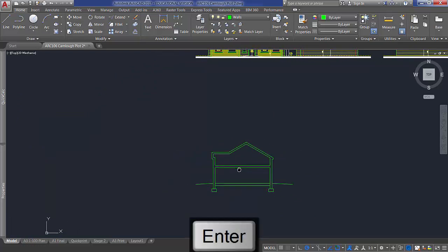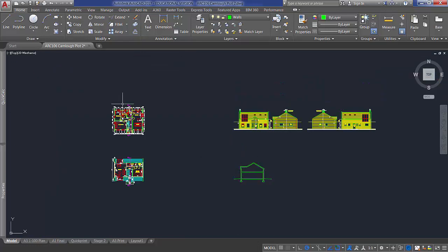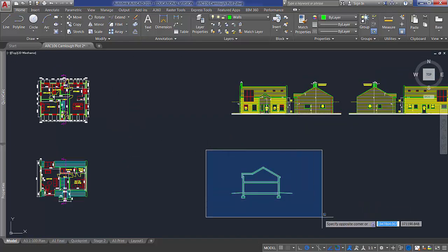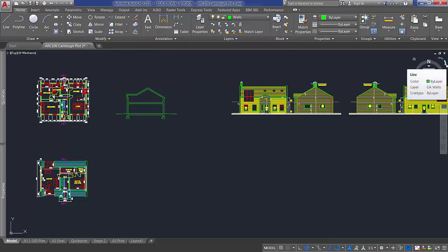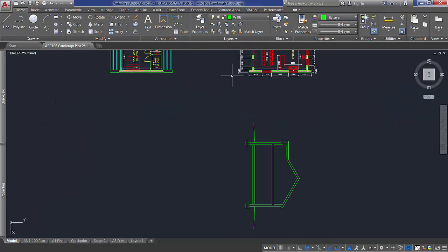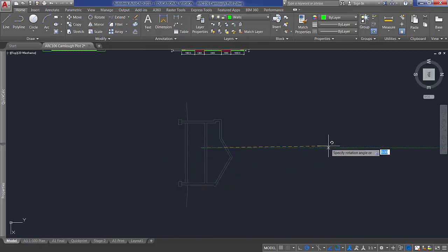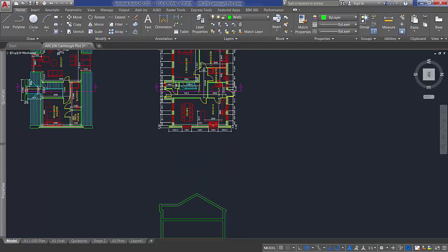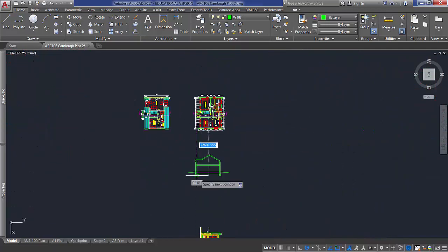And what you can also do is add in some internal elements to show roughly where the stairs are going to be. So to get that looking accurate, what you might want to do is move the section up there, and you can rotate the plan around like so, and rotate 90 degrees the other way, and then line that up with the section. So let's just get the section line there and bring it down.